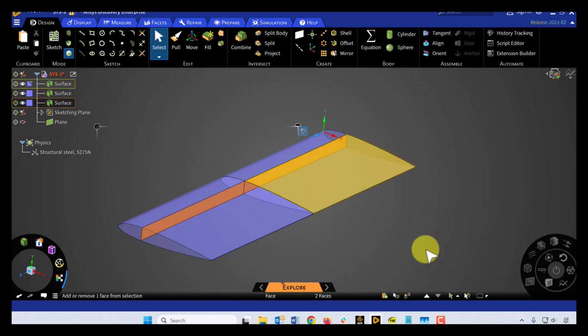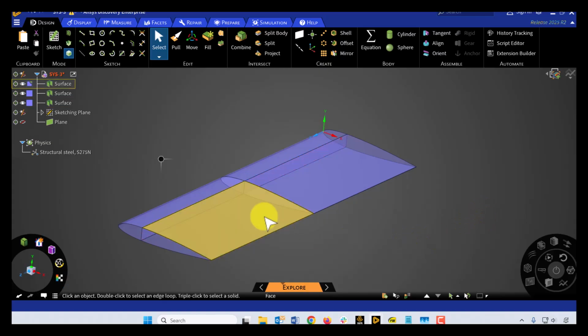In this case, there's only one spar, and in your design, you may want to use more than one spar and also play around with the location. And then there is the rib. So that's one part of the rib, and there's the other part. And again, there's only one rib in this initial geometry, and you may want to explore the effect of rib placement as well as changing the number of ribs. So how do we create this geometry?